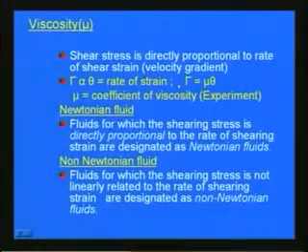So, Newton, after studying all these properties, derived the fundamental equation of Newton's law of viscosity. He observed that the shear stress is proportional to the shear strain du by dy, and he derived the equation tau is equal to mu into du by dy, where mu is the coefficient of viscosity. So, here the shear stress is proportional to the shear strain, and he expressed tau is equal to mu into du by dy, where mu is the coefficient of viscosity.